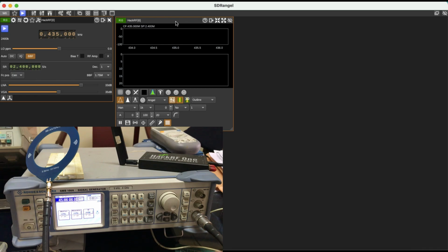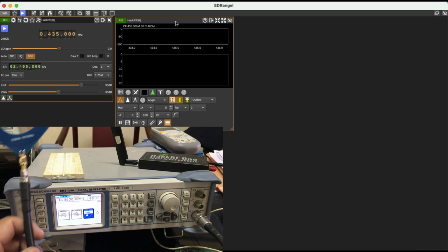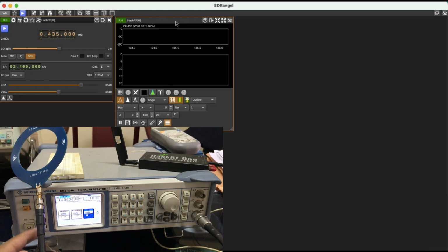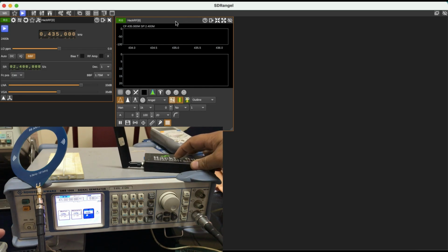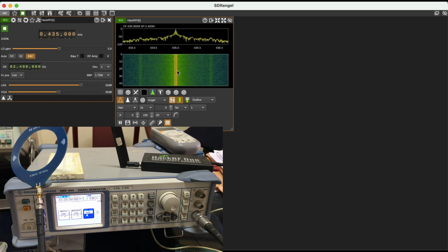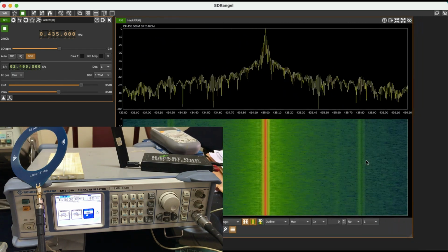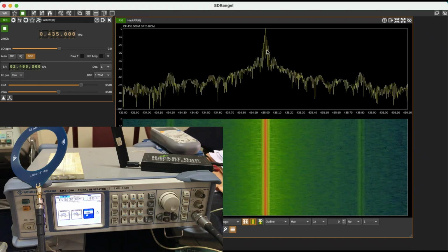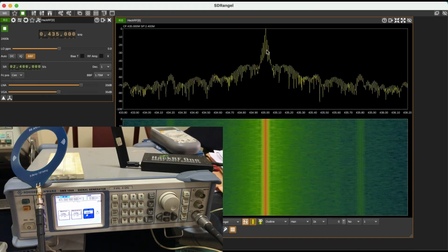and let's hit this button which is called RF on/off, or I can click on this button which says diagram. I can highlight the diagram and I can just press this in, and it will turn on my RF on. Now this antenna starts transmitting my RF signal at 435 megahertz. This is going to receive it, so you can see it in the same frame. And I'm going to turn on my SDRangel, which is configured at 435 megahertz. And I should be seeing a spike like this at 435 megahertz, which looks something like this. So that's pretty good. At 435 megahertz, we have a transmission happening.